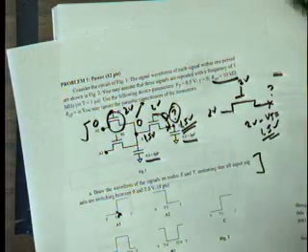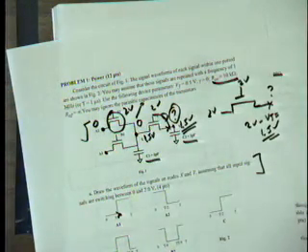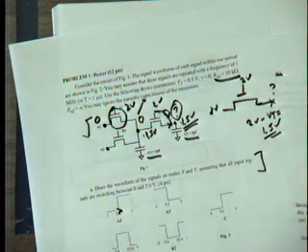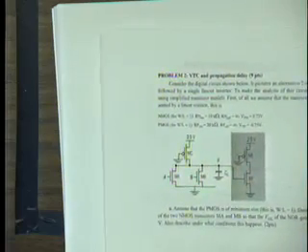We know exactly if it's going from 0 to VDD minus VT. What do you get as the power dissipation? It's CL times VDD minus VT. Remember that? There you have the factor that this power dissipation is not CL VDD squared, but CL times VDD times V swing. So the swing is not going all the way to maximum voltage here. That's why you have 2 volts times 1.5 volts. But let's stay away from this, and the rest of the questions are also basically on power dissipation. So let's ignore those for the time being.